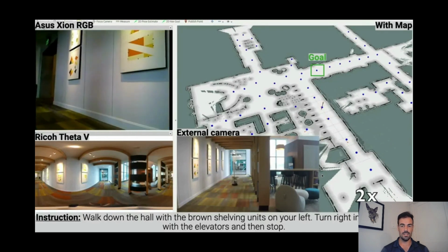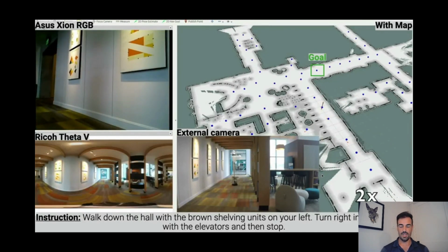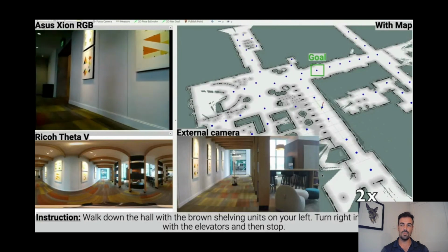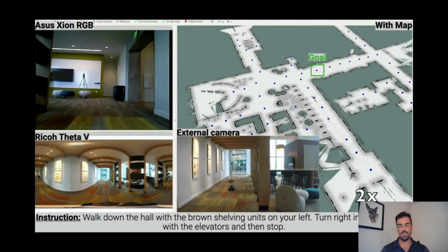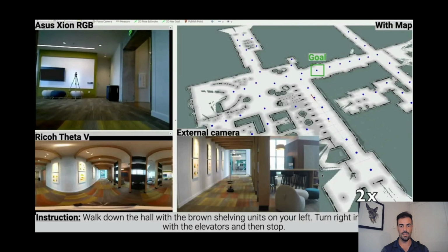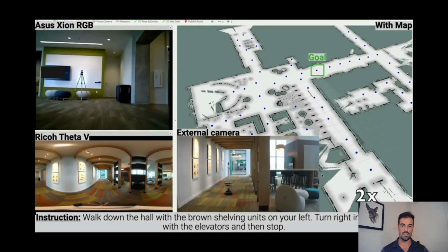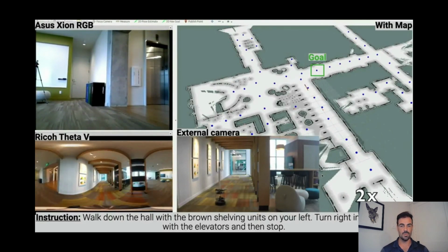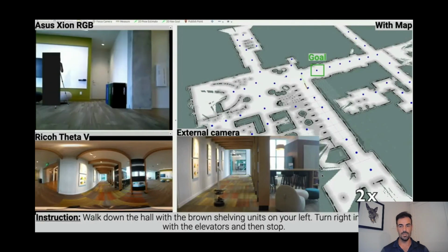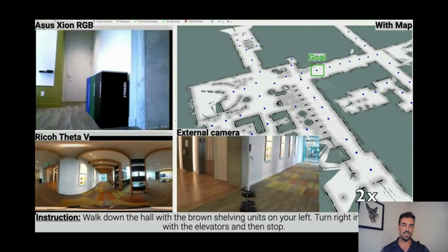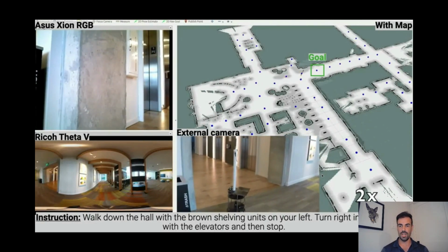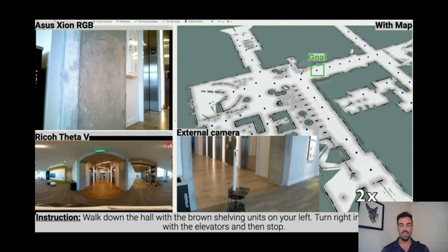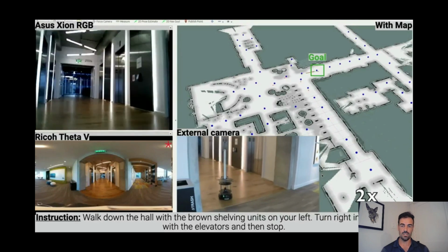Okay, you can see a second example here. The robot is navigating, and you can see that the map is already populated with the complete navigation graph and occupancy grid. So this is an in-between setting. This doesn't help with any of the language grounding aspects, but what it does do is eliminate the action space differences between the simulator and the real world. It's worth considering, I guess, that for a robot to operate in the same environment for a period of time, it's not overly difficult to collect an occupancy map and even the navigation graph in advance.